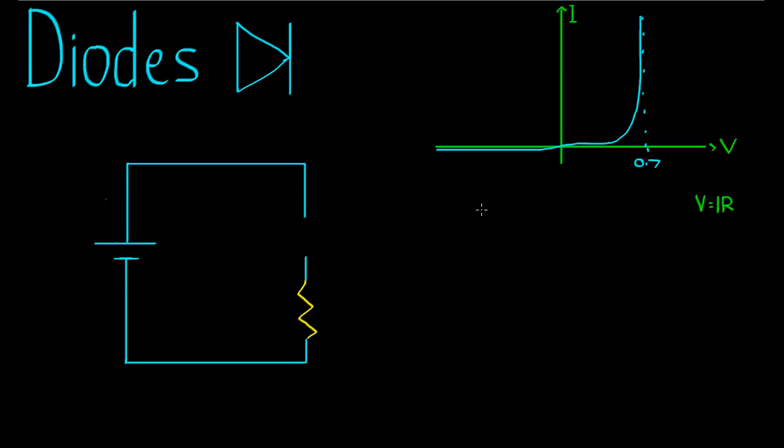To summarize the theory lesson we did on diodes, a diode can either be placed in forward bias or reverse bias. The definition of forward bias is if the current is flowing out of the battery this way, and you see the diode drawn like so, you assume the examiner is telling you the diode is in forward bias there. If the diode is instead drawn like this, that is a diode in reverse bias.